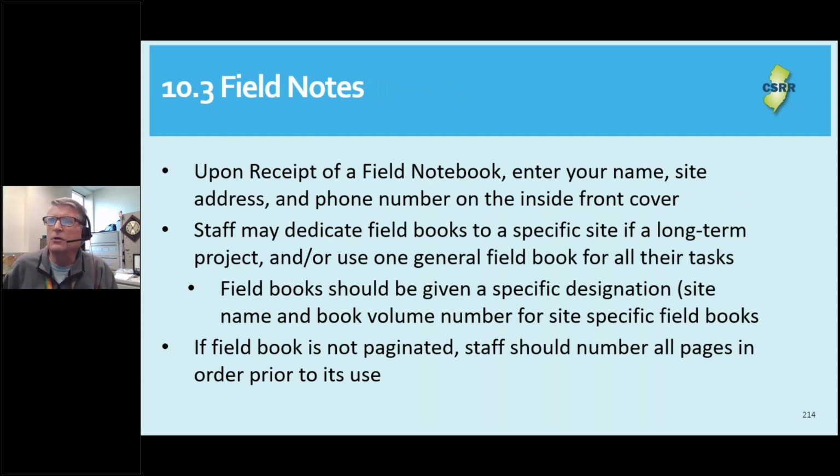Although the field notes are not required to be submitted to the DEP or other regulatory agency, they should contain contact information and site-specific information, which should be available upon request. If the field notebook is dedicated to the site and is used by several individuals, the contact individual should be identified for each entry in the field notes. Pagination is important. It ensures that the notebook is not missing any particular information.